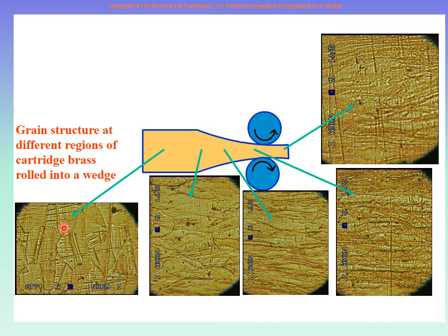So if you can see, there are standard large size grains. I mean, actually they are not large size, they are nanometer size, but grains are like this under the microscope. And under the same microscope, now the grains are very, very long needles. So you see, if rolling is being done, then because it is being rolled in this direction, it is being elongated. So the grains are also elongated like this.